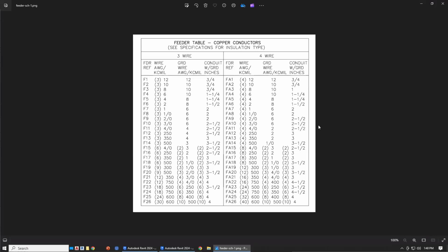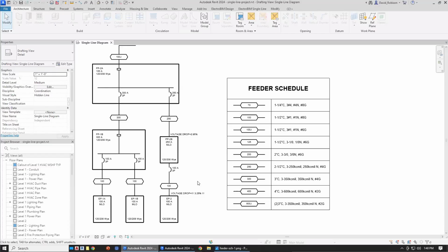So you actually can't cross out the F12 and just type in F13, because this ground size is the same. You actually need a new ground size in there. So that's why Design Master is thinking not in terms of IDs, but in configurations of wires and conduits, and then the ID flows from that. So to change this, you don't want to change this ID.